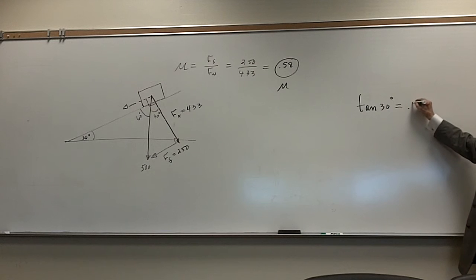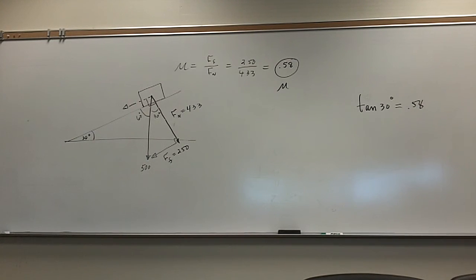So in other words, right now the way it stands, they're sitting there, they're sitting still. Because you may well look up and find out by looking at a book somewhere that the two materials you're talking about may have a coefficient of friction of 0.25. That block is not going to stay up there, folks. That coefficient of friction is too low for it to stay there.